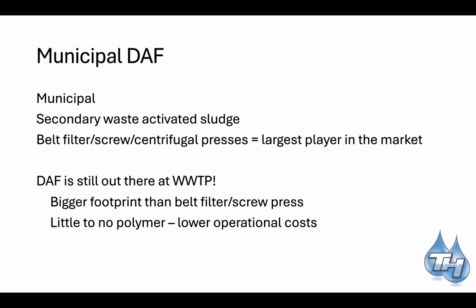So where do we find these things? There are still DAF systems out there in wastewater treatment plants in the municipal sector. They're great for secondary waste activated sludge, and they have a bigger footprint than their main competitor, but they use quite a lot less polymer. So overall, you have lower operation costs with a DAF system.